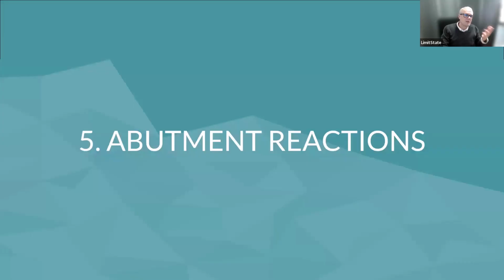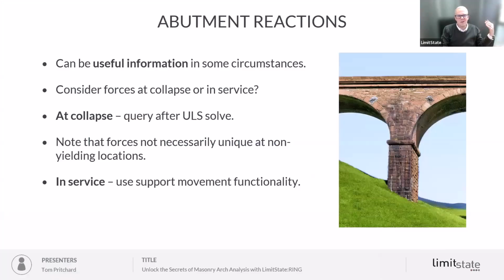The last thing I'm going to look at very quickly, I'm conscious that time is almost run out, is abutment reactions. So both at collapse and under service loading, understanding the forces at the supports can be very useful. For instance, if you're doing work at the foundation level, you'll need to think about a collapse. You can just query the forces after performing a normal and ultimate limit state solve within Ring. But we need to keep in mind that the forces aren't necessarily